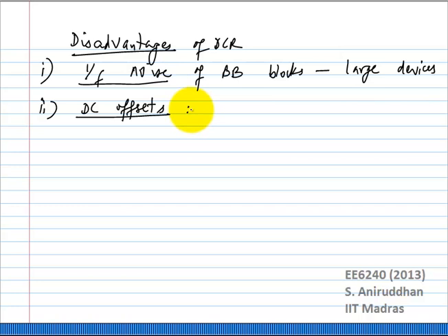Any other kind of DC offset you can think of that could cause a problem? Obviously the inherent DC offsets of the amplifiers themselves are a problem, but I think the solution is the same. You have large devices that will give you better matching and it will give you better DC offset also. Solution for 1 over F noise and DC offset are similar, right? But can anything else give you something which looks like a DC offset? We have seen this before.